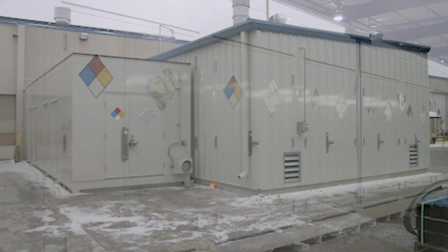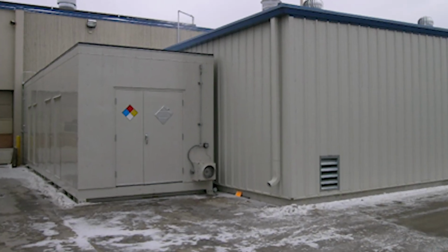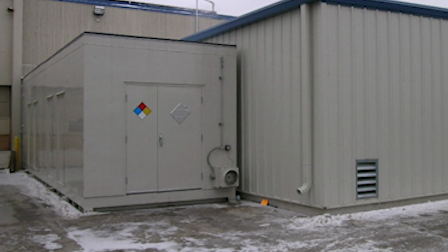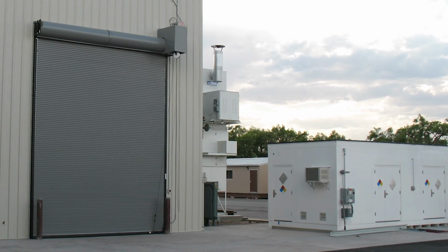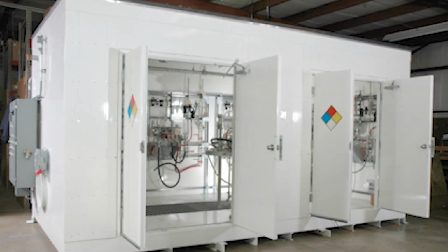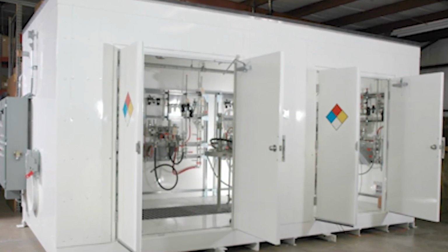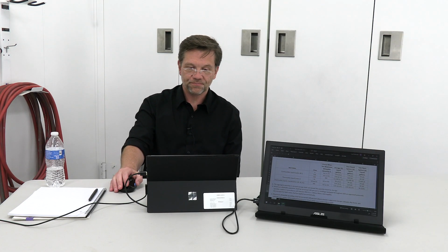Highlights of the requirements include fire-rated construction based upon the size of the storage building and if it is located indoors or outdoors, designed to be capable of containing more than the MAQ, electrical area classification, again, based upon the location of the sources, and where dispensing or filling is performed, the minimum ventilation requirement is 1 cubic feet per minute per square foot of floor area or 150 cubic feet per minute, whichever is greater.